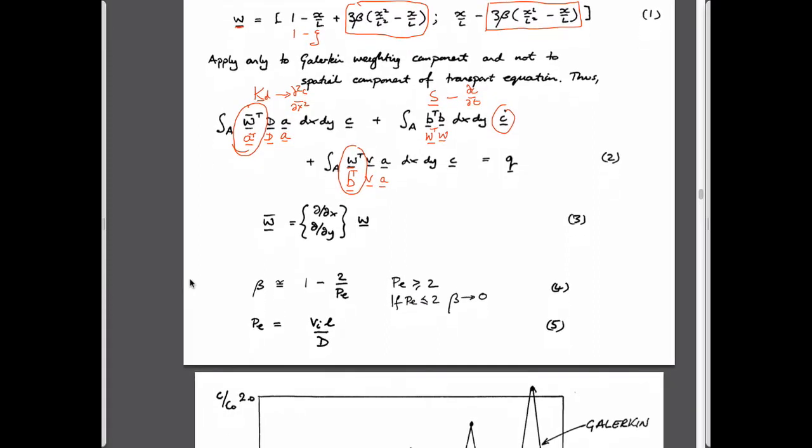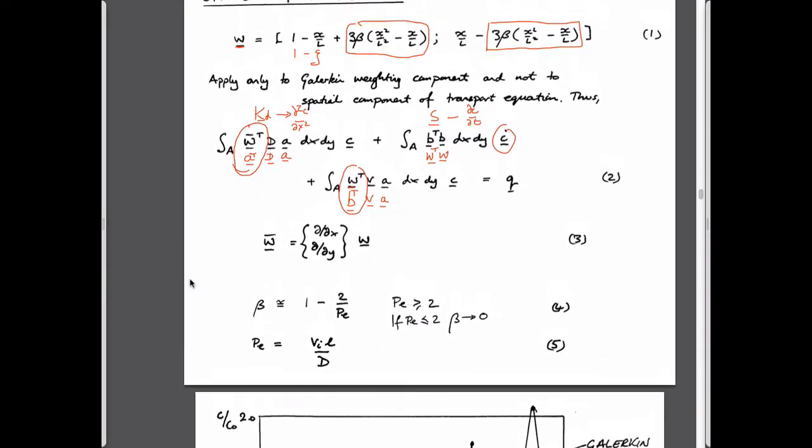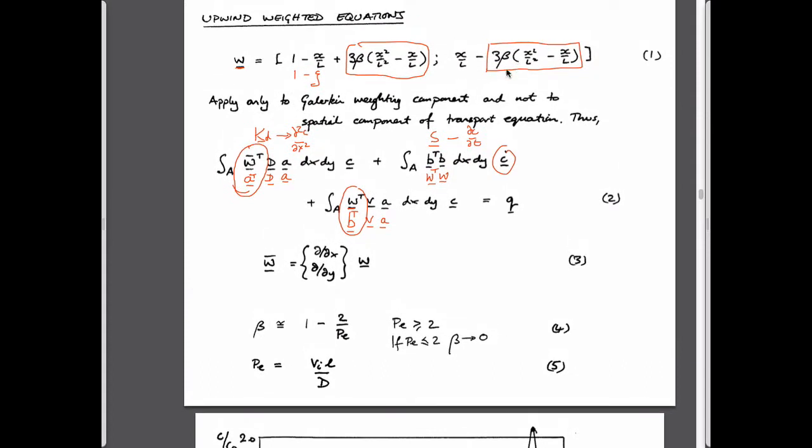What else? There is a stability criterion. There's a term in here, obviously. So I didn't explain that perhaps in great detail, but these are just functions of location in the element, relative coordinate in the element, and relative coordinate squared. So this is a term. This describes the magnitude of the upweighting. Obviously, when this term is 0, then it's just a linear shape function. When this term is equal to some bigger number, then probably with a ceiling of 1, I'm thinking. Yeah, with a ceiling of 1. When this is equal to 1, then it's maximally upwind weighted.